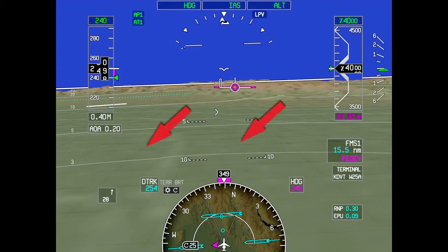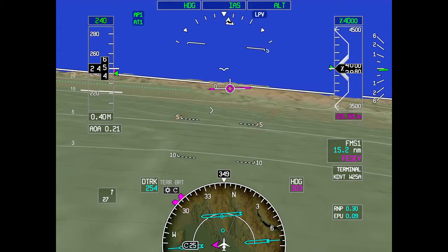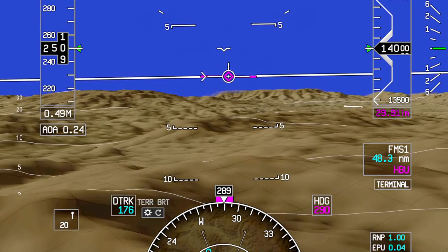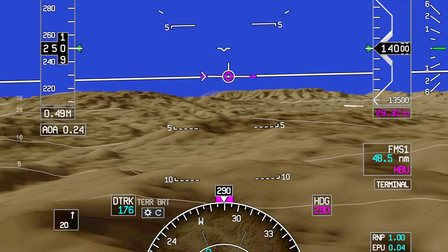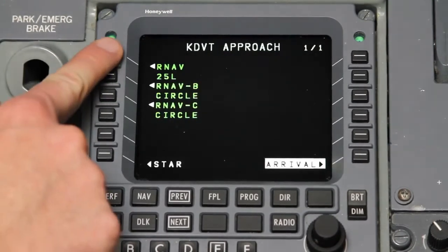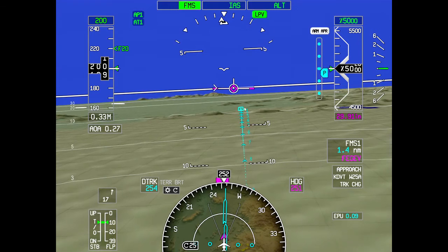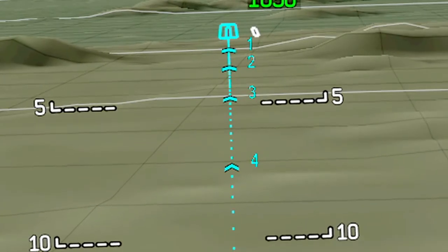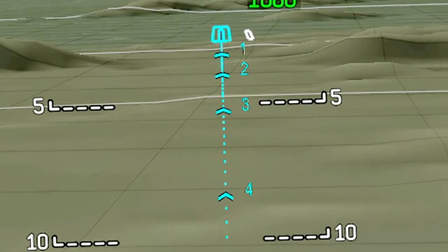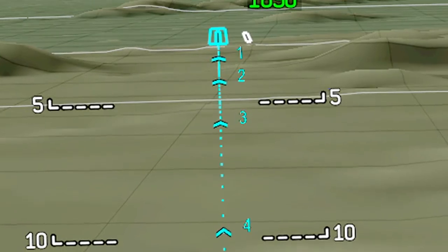Grid lines are displayed over the terrain and depict an approximate north-south and east-west grid. The grid lines are subtly overlaid on the terrain image to enhance 3D perception. In SVS 2.0, the arrival runway selected in the FMS is displayed with a runway lead-in line and distance markers. The distance markers are placed at 1-mile intervals and are a supplemental tool that can be used to assist in maintaining situational awareness and a stabilized approach.